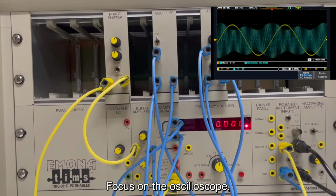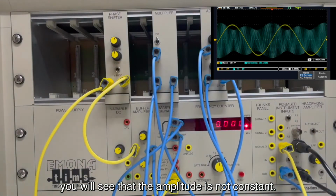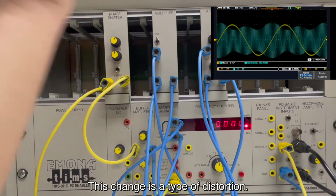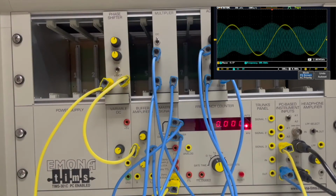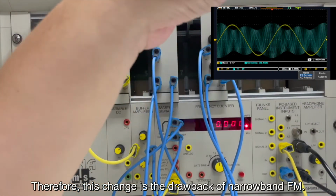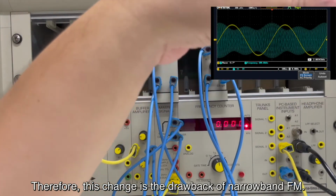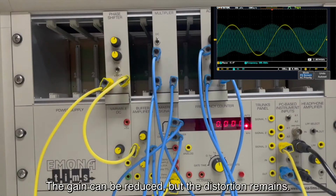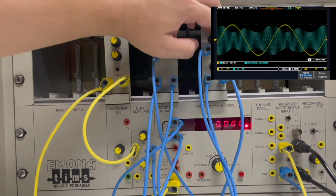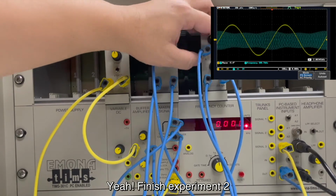Focus on the oscilloscope. You will see that the amplitude is not constant. This change is a type of distortion. In fact, the amplitude must not vary. Therefore, this change is the drawback of narrowband FM. The gain can be reduced, but the distortion remains. Yeah, finish experiment 2.